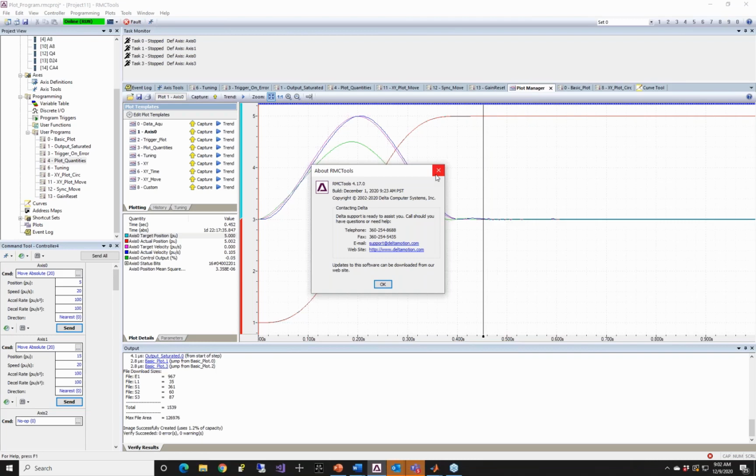But if you have specific tolerances, maybe you don't want to use the following error for one instance or another, monitoring that skew is great. It's a nice thing just to have on a plot as well, because you can put it on its own scale group, and it makes it a whole lot easier to see how well each of those axes are tracking, and see if you need to go back and maybe do a little bit tighter tuning.